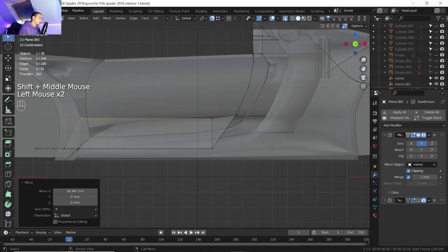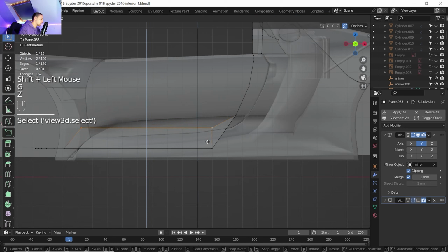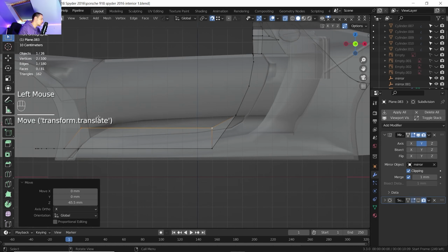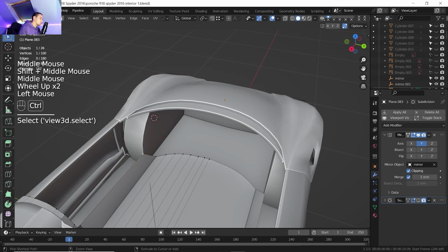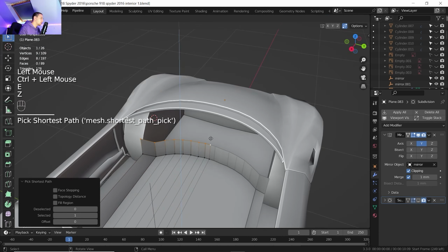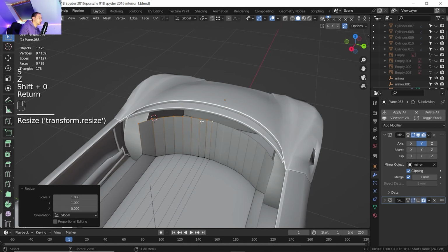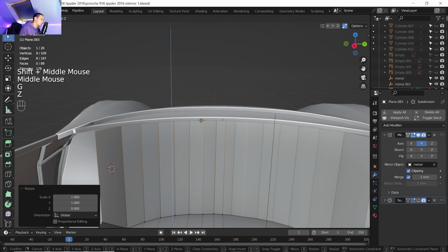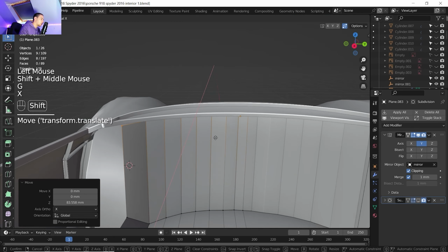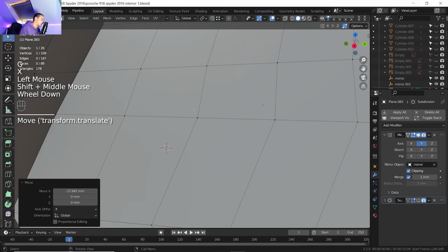Let's take a look at the side view. So that's pretty good. Maybe that's too much. I'm gonna leave it to something like that. Here I'm gonna go to something like this, then just like that. So now with these points, I'm gonna extrude going on the z-axis. Let me just scale them on the z-axis to 0, to something like that. So it's much easier for me to just go with them around this area. I'm gonna go a little bit more on the x-axis, and also with this point around here, x-axis.